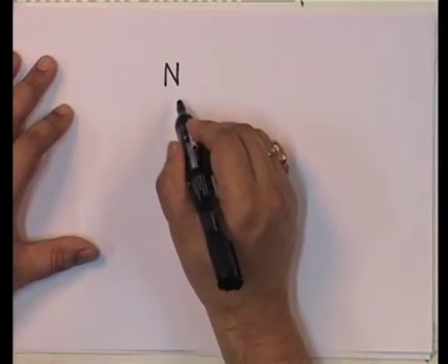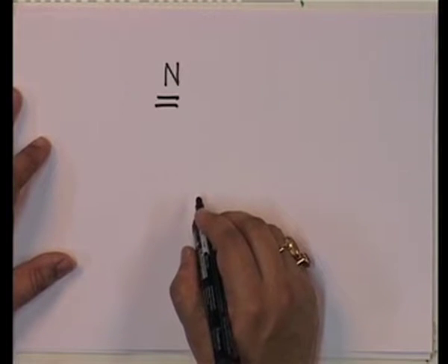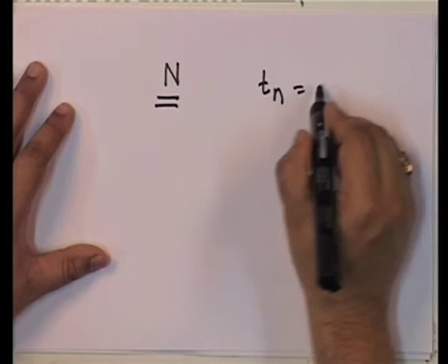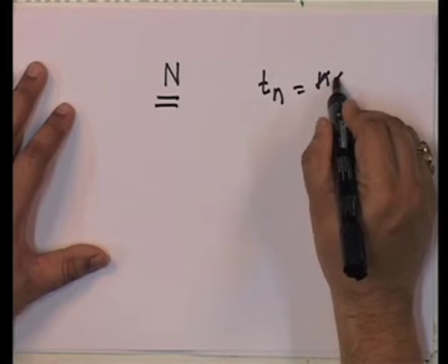Essentially you have to worry about the frequency resolution, so your Tp is determined by frequency resolution, and delta t to a certain extent is determined by the Nyquist frequency. Nyquist frequency means how many frequencies I want to consider, and those are issues that come from practice and from knowing what kind of structure and load I have. All I am trying to say is that typically the value N is known. And understand that this means T_n is equal to n times delta t.